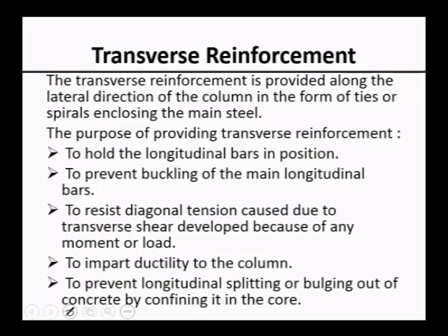To prevent the longitudinal splitting or bulging of the concrete, it will confine the concrete within the size. Okay, it will avoid the bulging of the concrete. Therefore, the strength of the column will increase. These are a few of the points we have to keep in mind, due to which transverse reinforcement must be designed.